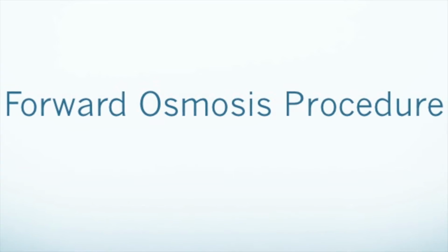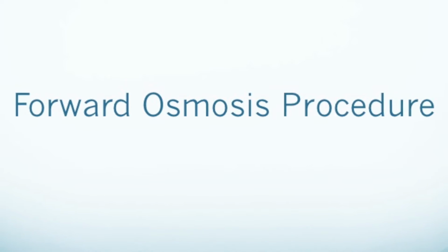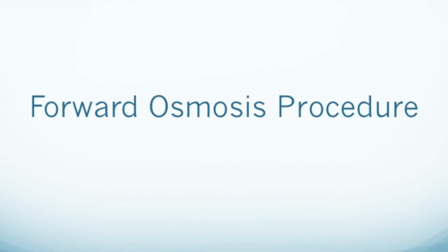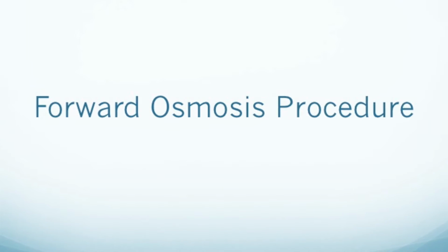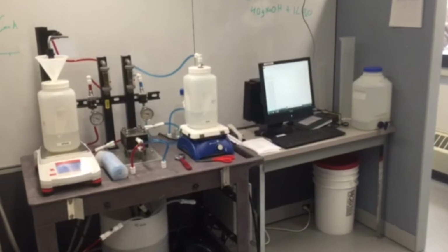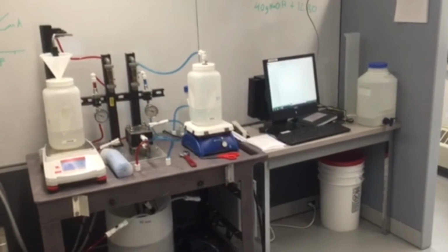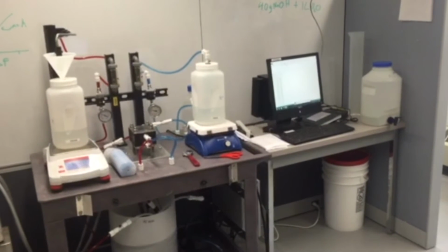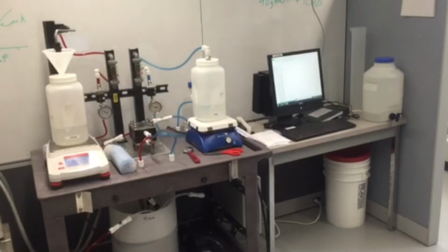Forward osmosis procedure. Begin by preparing a 1 liter solution of 5 molar NaCl and use a stir bar to completely mix the solution. Place the stir bar in the blue feed tank and fill the feed and draw tanks with 2 liter distilled water. Turn on the chiller and make sure the water level is between the designated lines. Make sure all fittings are connected.